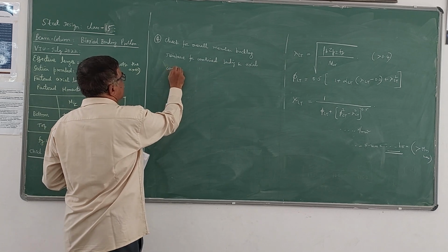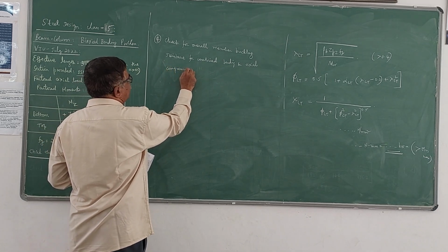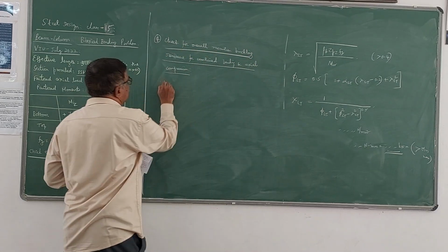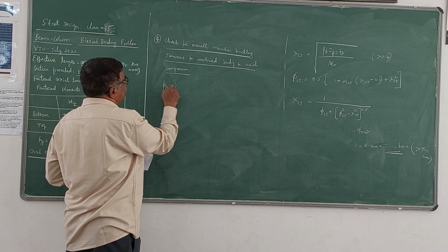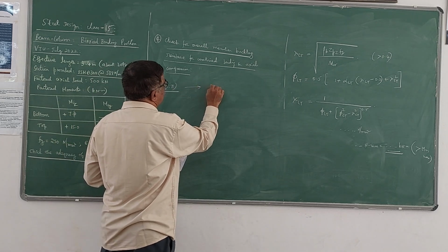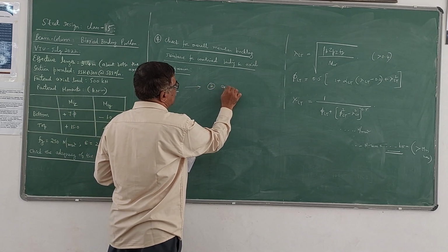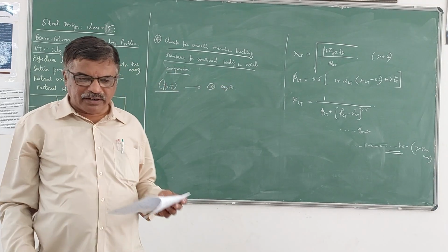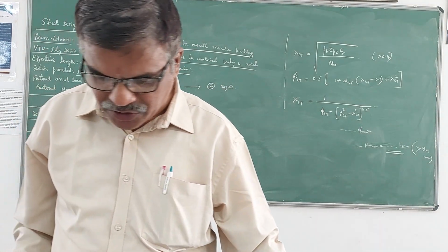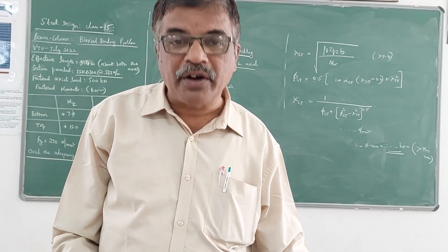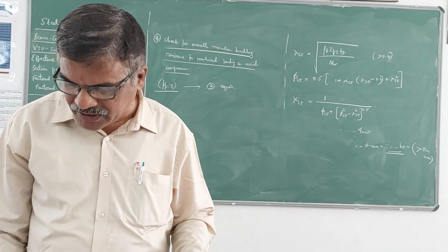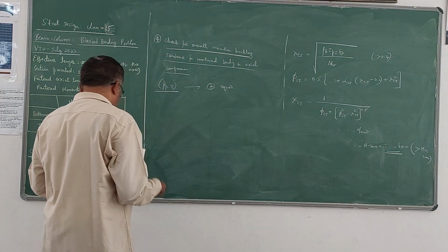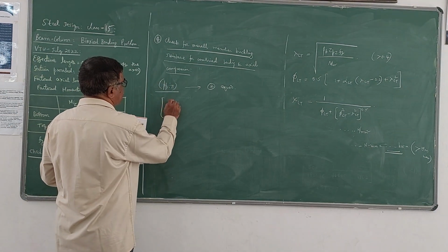Here we have to consider both the effects of bending as well as axial compression. So we have to refer to page 71. There are two equations for biaxial bending, so you have to refer to both. If it is uniaxial, there is only one equation, which I have done in the last problem. So here we have to use two equations. I am going to write these equations. We have to calculate all those parameters which are required.